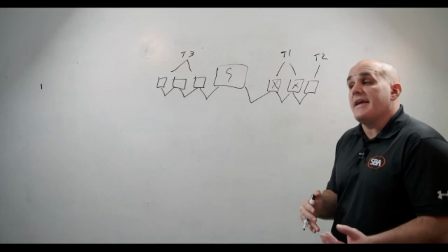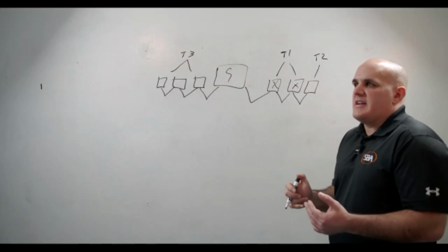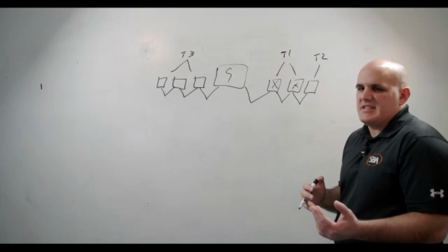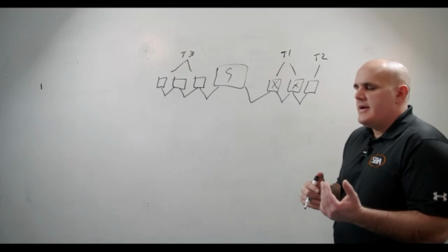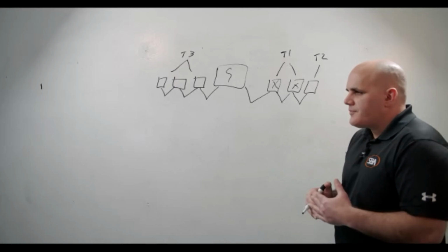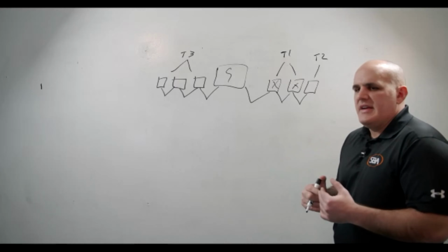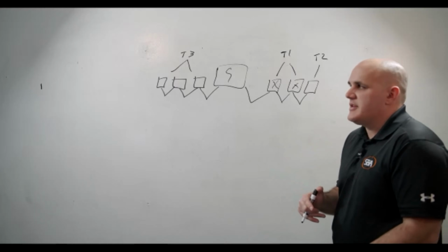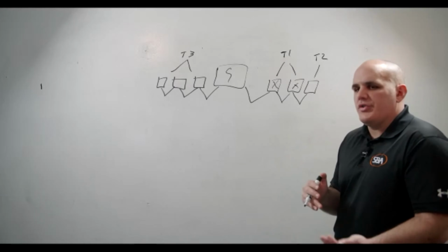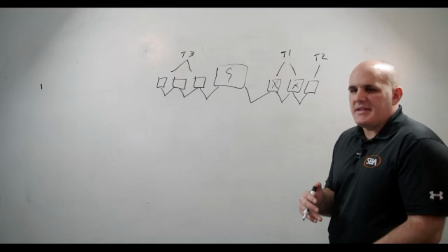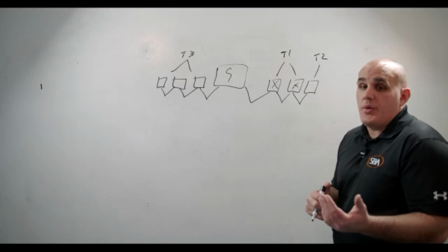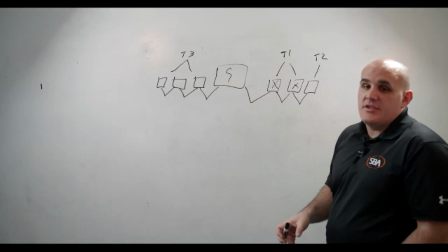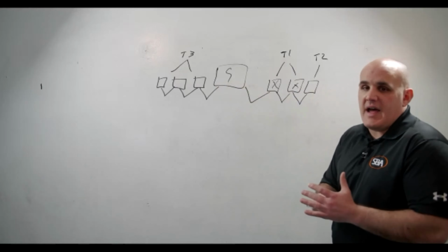I used to say, get a transformer bank of 380 plus VA with all those transformers stacked into a 16 by 20 box and put it in the plenum. I don't advocate that anymore, because if you lose the 120 source going to that transformer bank, you lose all those transformers. By having multiple transformer banks on multiple 120 sources, you segment your network electrically, which makes it easier to troubleshoot and more reliable.